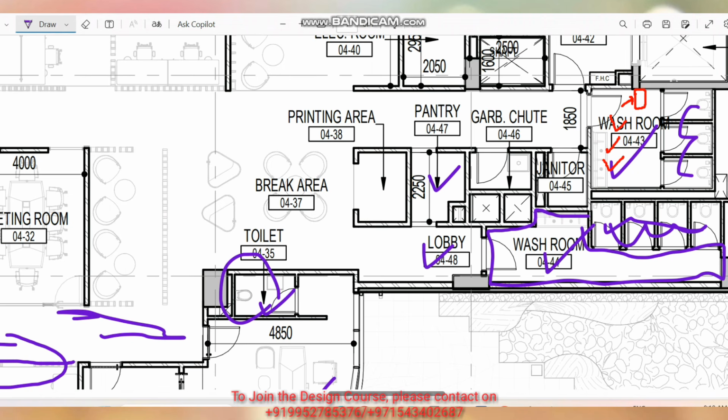Because here what is the concept is, for example, if you provide the duct here, you can drop the fresh air. You can drop the pressure at this point. So this exhaust, for example, let's say that 75 liter per second we have to throw as exhaust because of the 3 water closets. To compensate the exhaust, it will consider the fresh air from this area. So because we are dropping the fresh air at this point, this fresh air will be circulated here. Okay, so for this small area we don't need to provide the exhaust. Similarly for this area also, this area is very small.